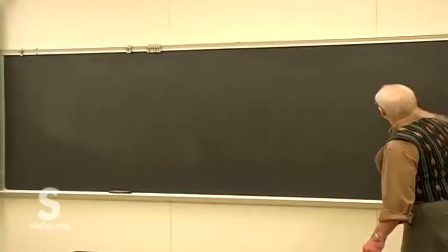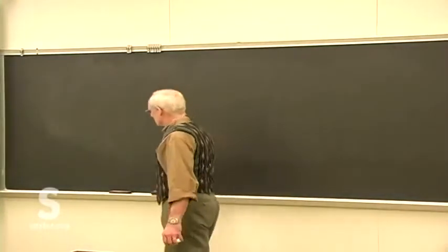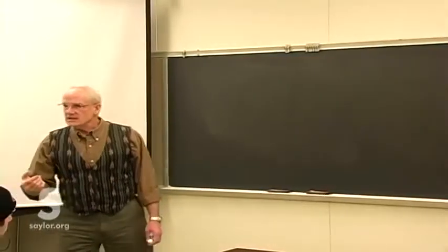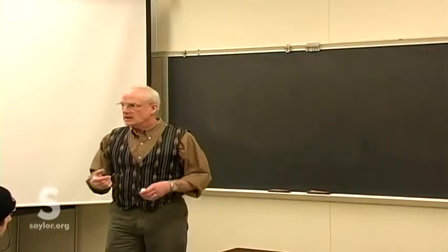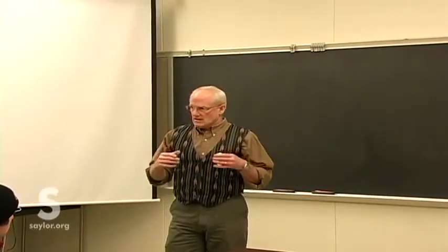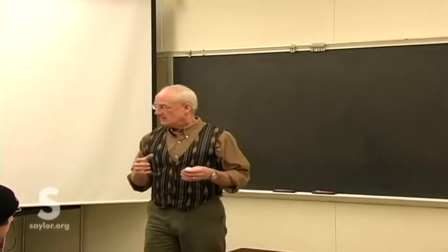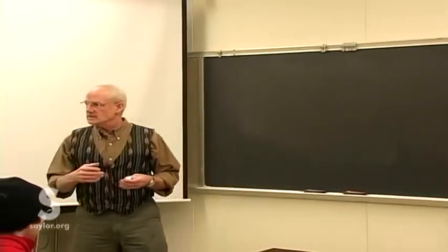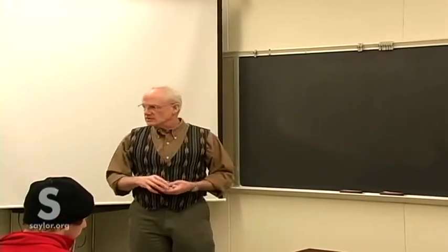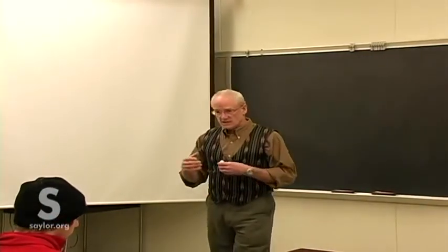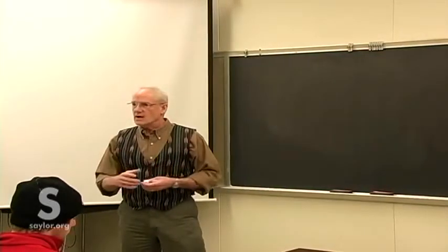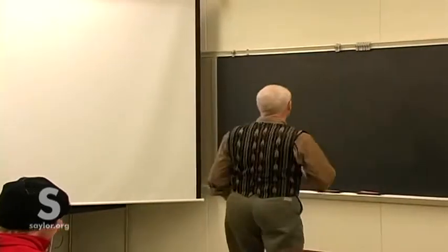One thing we will have to concern ourselves with in a little bit, probably on Monday we'll start with it, is that the failure doesn't necessarily mean that the piece breaks apart and can no longer maintain any forces. It could be that the structure elastically deforms enough so it no longer serves its purpose. It could be that under load some of these members deform enough that other parts in the structure don't match quite, and then the piece won't quite work.